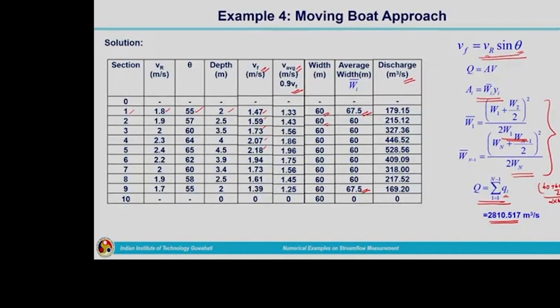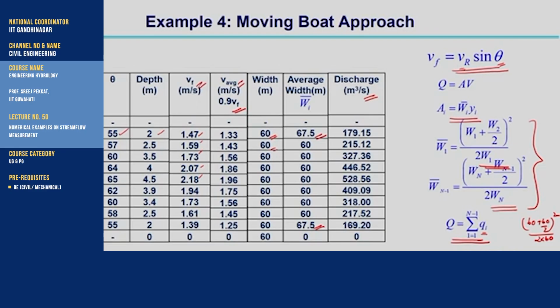So, based on that we are computing the area to be half into base into altitude. All other intermediate strips you are just calculating the area as a rectangular strip. So, that way we have considered for making the areas of this triangle and the rectangular strips to be similar, we have come up with the average width Wi bar, so that we can compute the area by multiplying average width by depth. So, that much about different methods which we have explained during the streamflow measurement discussion.